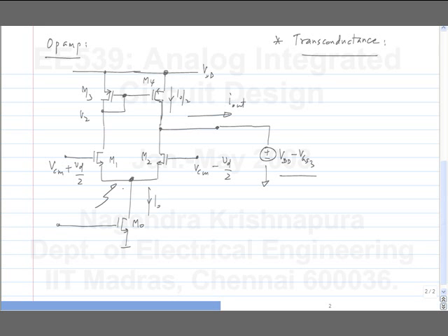Yeah, but the circuit is not symmetrical. So technically that's not a correct thing to do. This circuit is no longer symmetrical. It's not like when we loaded the differential pair with two identical resistors. It's not exactly symmetrical, so we cannot say that the tail node increment is 0.